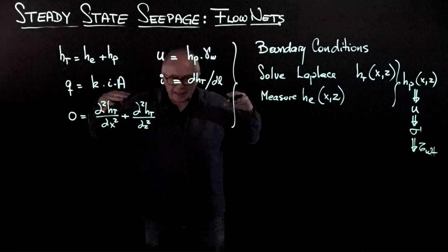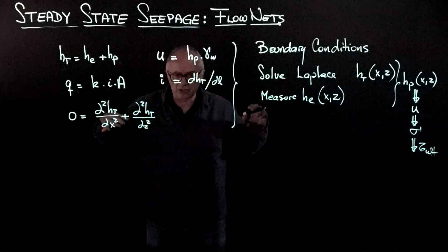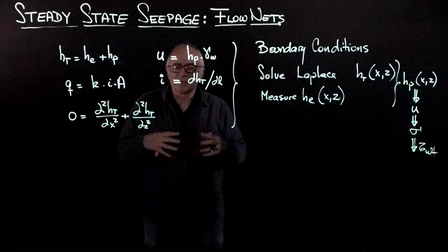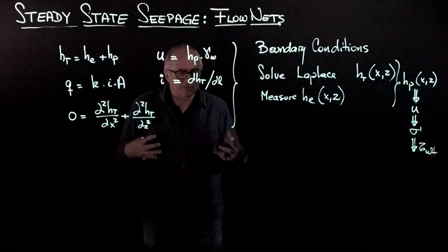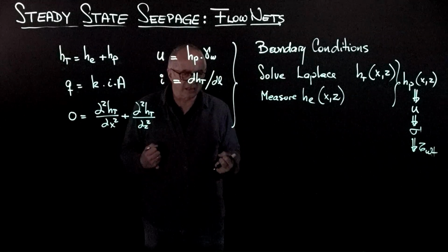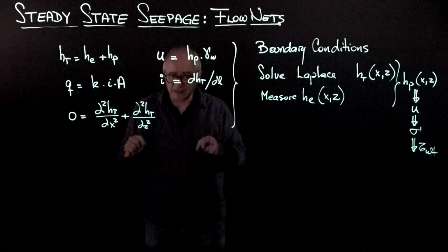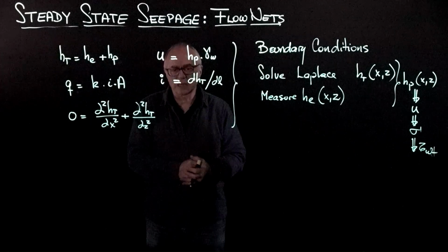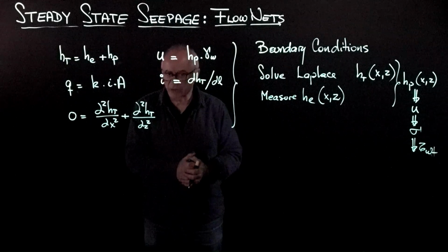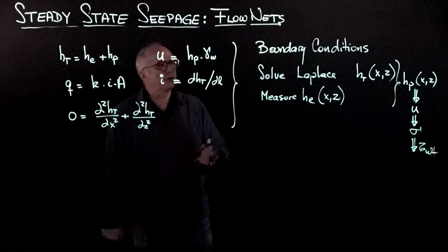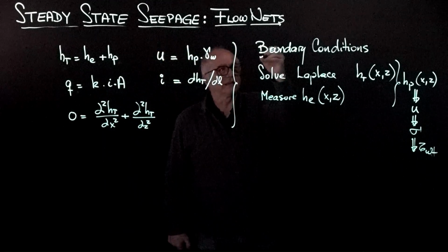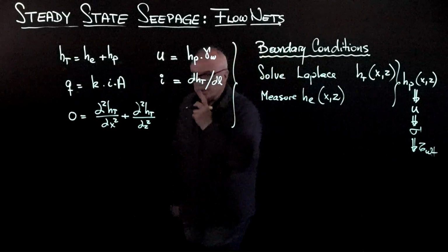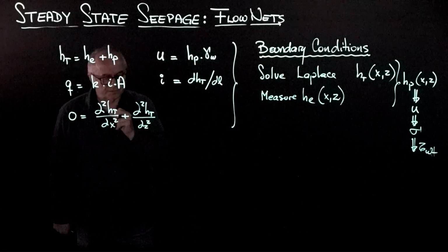Identify what the inlet and the outlet conditions are, and the boundary conditions for flow, because that perception of the problem is critical for an engineer, but furthermore is critical to feed numerical solutions and to be able to rely on the outcome. So this is indeed probably the most critical starting point. What are the boundary conditions?